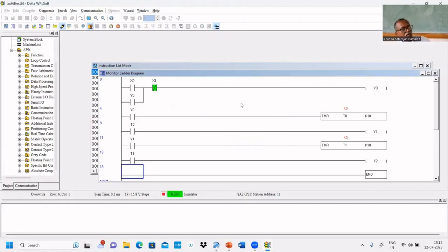In the PLC, there is a switch to run the program. That is called run mode. There is a switch to turn on as well as to keep this in run mode. If you keep this in programming mode, you can upload your program. That and all you will learn in the lab. While uploading a program, it should not be in run mode. While the uploaded program has to run, you should keep it in run mode. Yes, the program is ready to run.